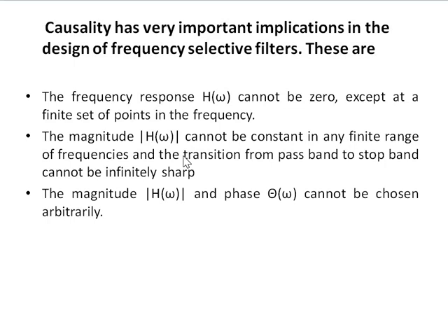The second is that the magnitude of h of omega cannot be constant in any finite range of frequencies, and the transition from passband to stopband cannot be infinitely sharp. The third is that the magnitude of h of omega and phase theta of omega cannot be chosen arbitrarily. Ideal filters cannot agree with all this.